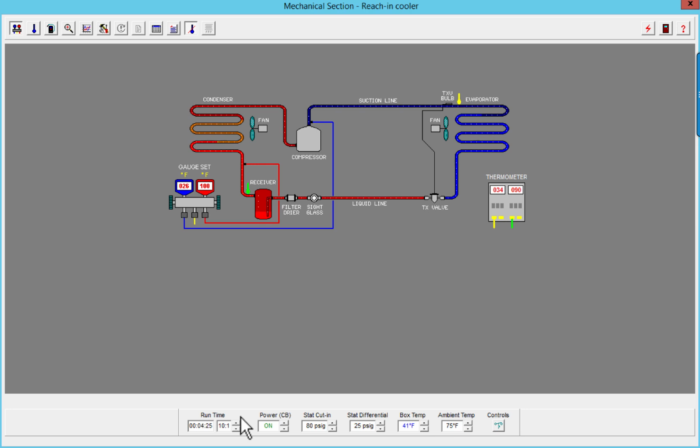So now we have a system that is running properly. 8 to 12 degrees superheat, 26 degree evaporator temperature, 100 degree condensing temperature. Outdoor temperature 75 degrees, 100 degrees. We're 25 degrees above ambient. I'm going to accept it for now. Okay, so that's what we do when we're running perfectly.